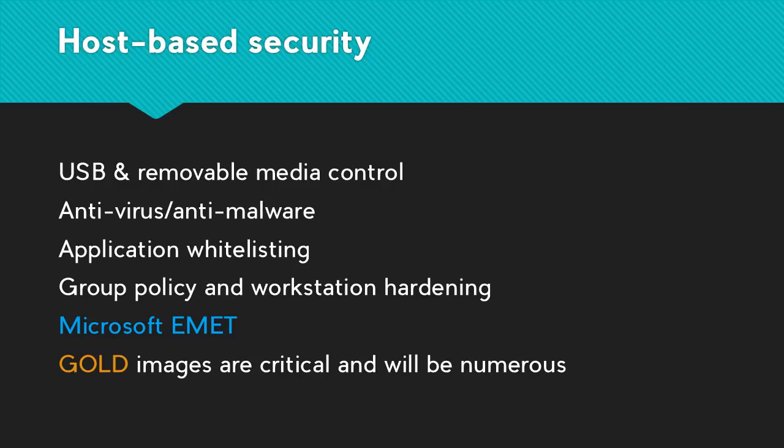So understand, you can use group policy to push out your configurations and make sure your configuration management is the same. You can harden your workstations and restrict the types of applications that are run. You can use whitelisting on Internet Explorer or the browser, but just don't use the same group policy for engineering workstations as you do for enterprise workstations.